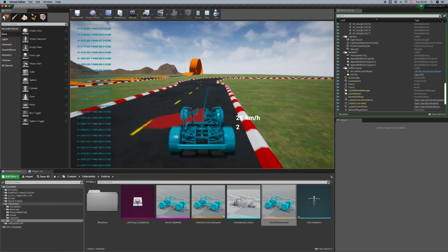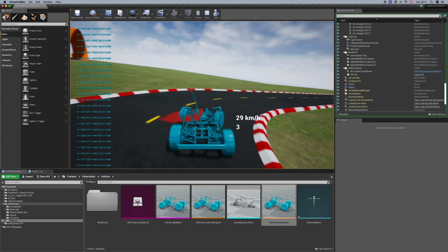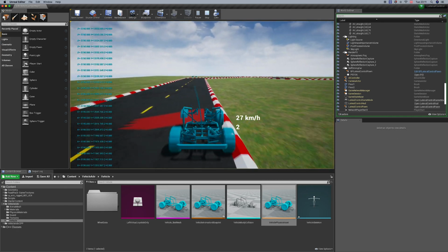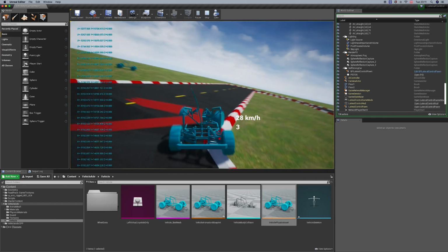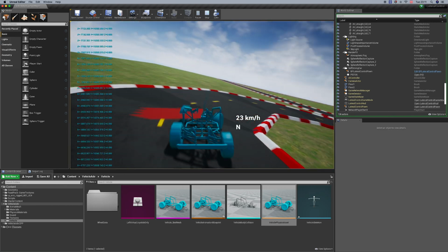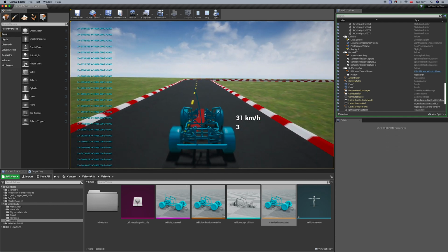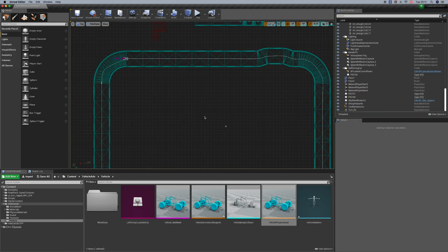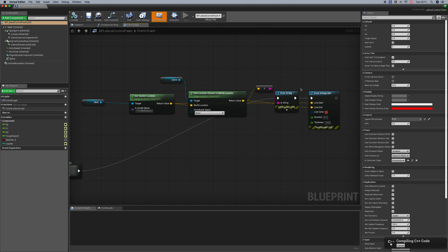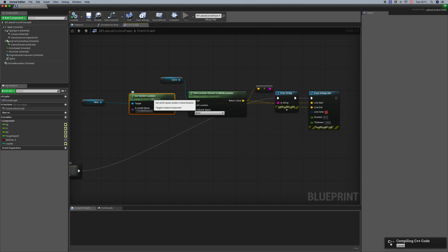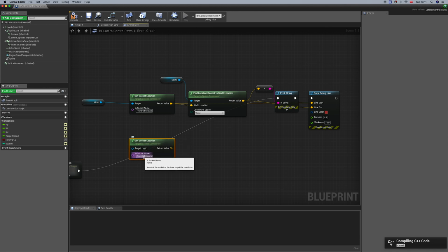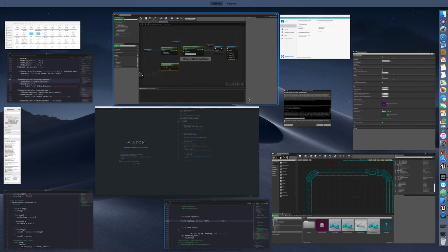So this is basically now the vector between the front of the vehicle, or the front reference point, and the path or spline. I think we need to move that bone or that reference point a little bit more ahead because it's not really a head vector. But let's keep it as it is now because it might be enough. What is important for the pure pursuit controller is not this vector, actually, but the second vector, which is from the rear center, which is here. Actually, it's called, in our case, let's copy it from there. It's better. The antenna root.